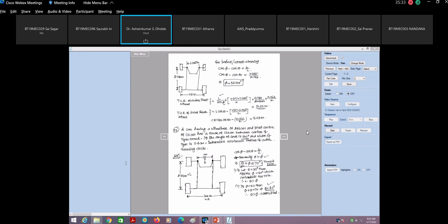So please don't take that theta plus phi has to be exactly 70 degree. This is true as far as most of the cars which are running on the road, but in specific vehicle for specific steering system which is designed by the designer, there can be exceptions.